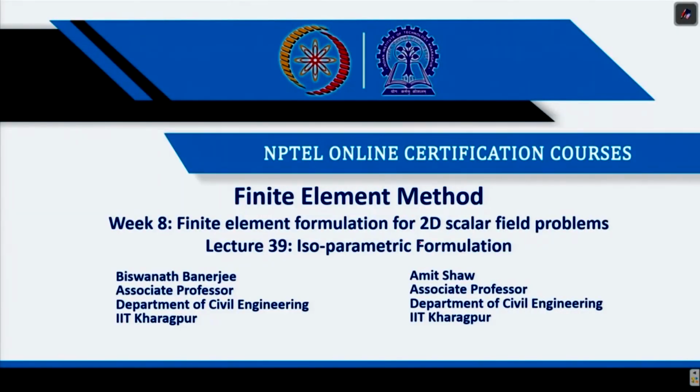Hello everyone. Today we will discuss Iso-Parametric Formulation in finite element method. You see, the idea of finite element method is we have a domain and then that domain needs to be represented by a collection of elements. And for these elements, we write the equations over each element and then assemble and finally solve. But the domain is represented by a set of elements. We already know what triangular elements are and we know how to write shape functions for triangles.